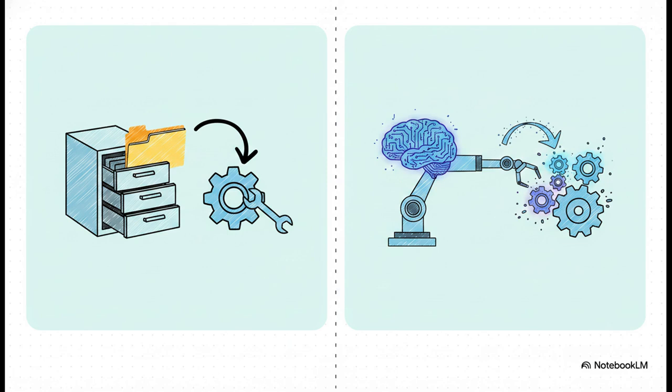Now, within CAP, you've generally got two distinct flavors. And notice the stark contrast here. A variant system is kind of like a super organized digital filing cabinet. It scans the new part's code, finds a similar older part in the database, pulls up that old plan, and says, "Here, just tweak this." Generative systems, on the other hand, far more advanced. They act almost like an AI, using deep decision logic to write completely optimized, brand new plans from scratch, based purely on the geometry and what the factory can handle.